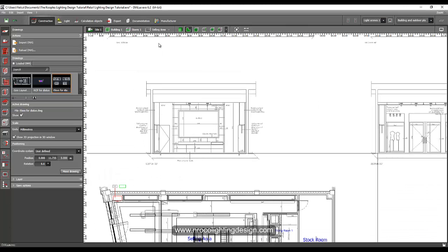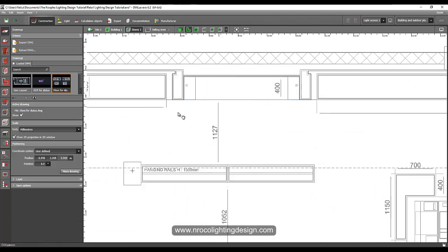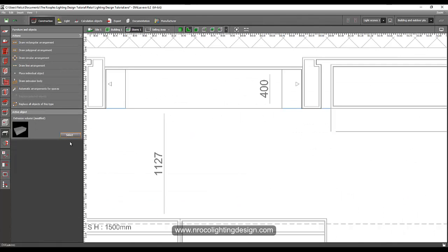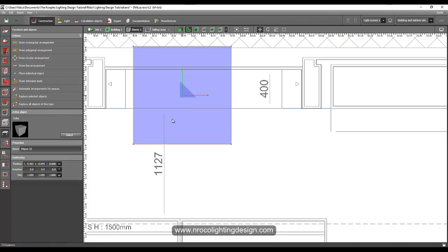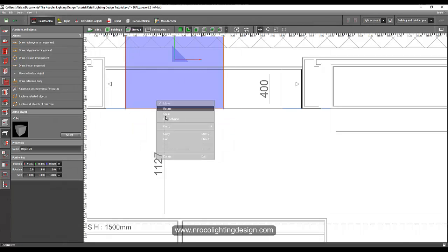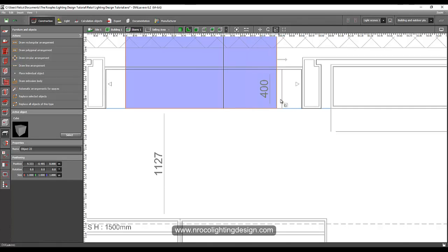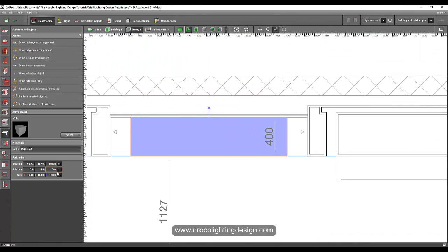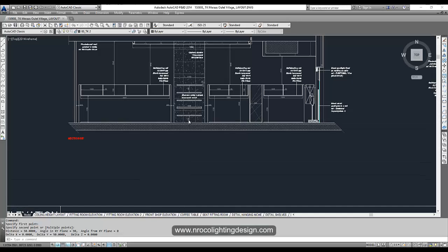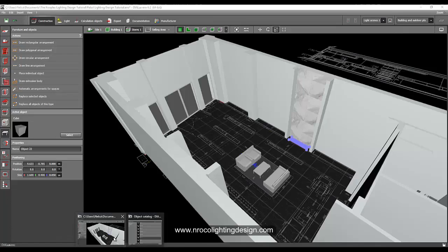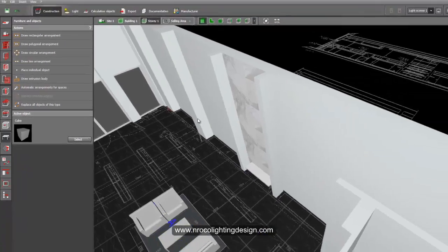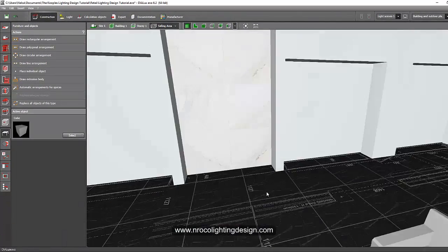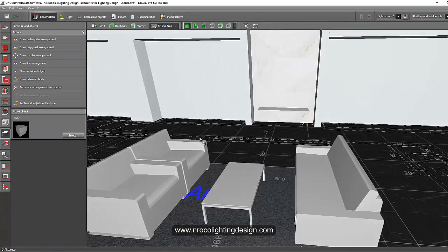So go to the Dialux, go to the story now. We don't need to copy that from the elevation. We're just going to do it here in the plan. And then let's go to the object, select this cube, and place it there. And then scale it accordingly. And then it says that it's 0.05. There you go. And it says that the height is 450. So let's go and move it 0.45. There you go. So now we have our first shelves.